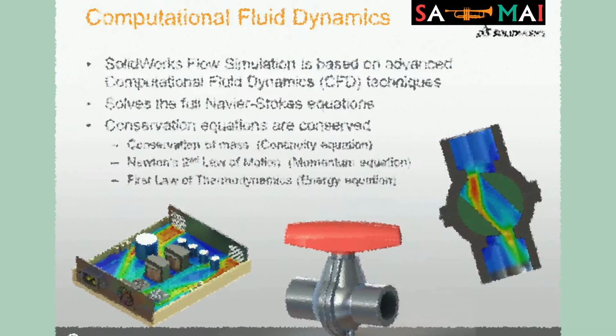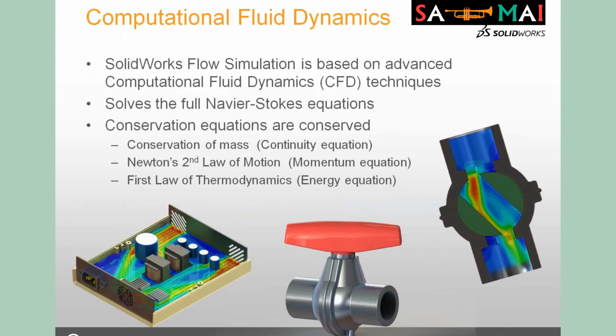So let's switch gears here. Let's go from finite element analysis and switch to computational fluid dynamics, or CFD. SOLIDWORKS Flow Simulation is based on advanced CFD techniques. It does solve the full Navier-Stokes equations, so that means conservation of mass, conservation of momentum, the momentum equation, and then also if you're solving for thermal, the first law of thermodynamics, which is your energy equation.